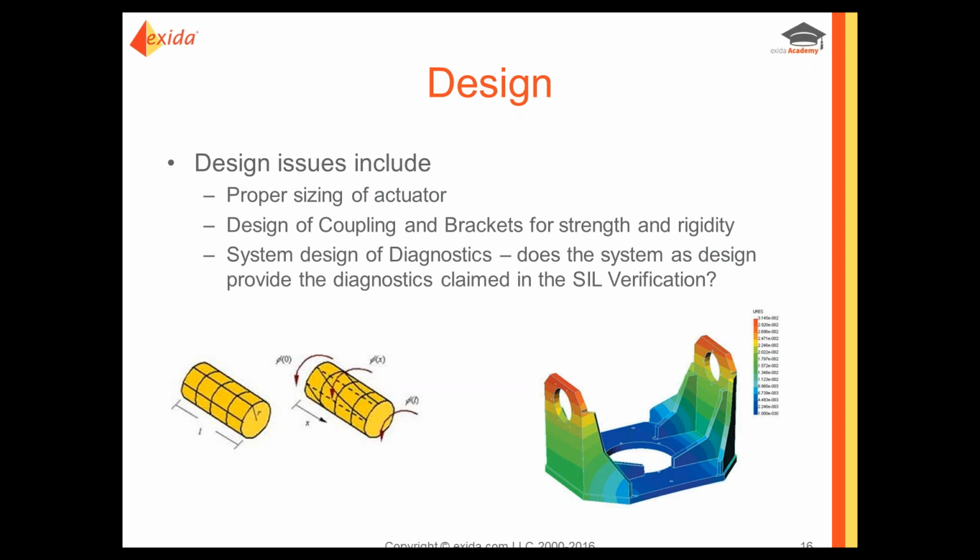And there's a question. The question was, can we get the PFD average value for each valve component from the vendors? You should be able to get failure rates for the devices that the manufacturer is making. They should have an FMEDA with failure rates for their valve. They also should be able to tell you whether or not they've included coupling in that.